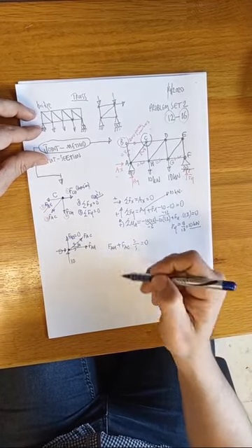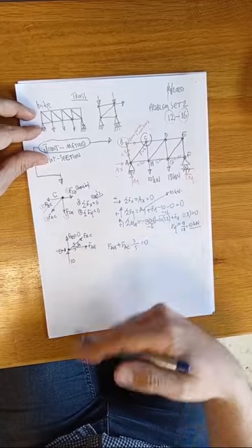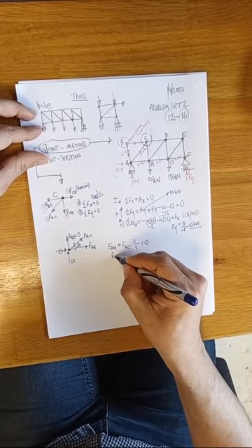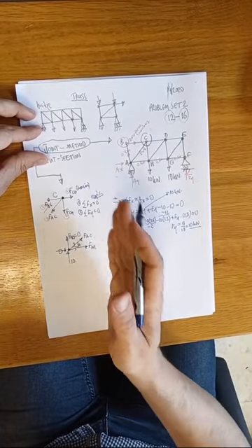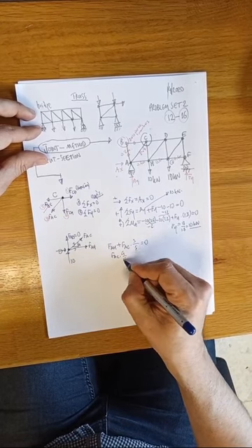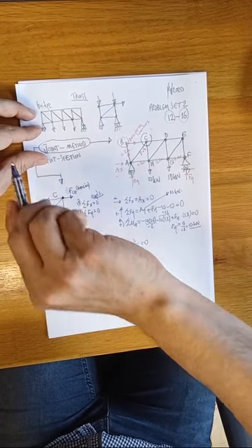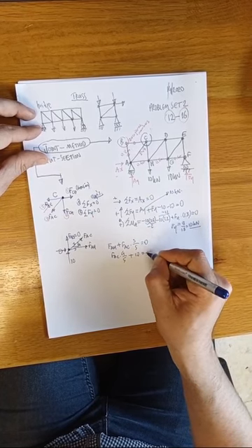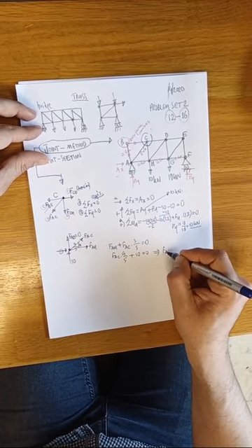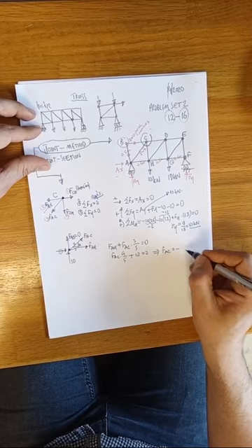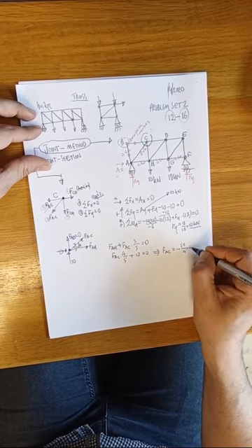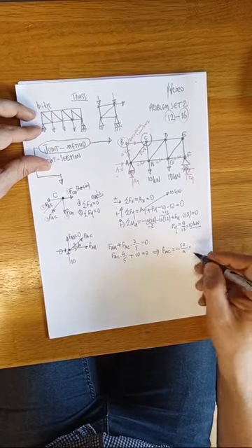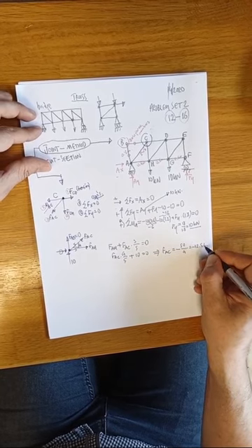In vertical direction, FAB, which is 0, skip that. So let's write FAC, but this time the sign of that FAC vertical component must be plus 10 is equal to 0. So this gives us what? As you see, FAC is equal to minus 50 divided by 4, or 25 divided by 2, or minus 12.5